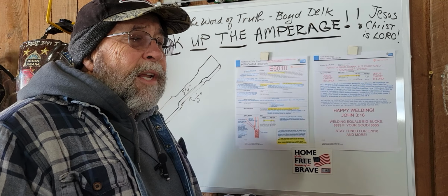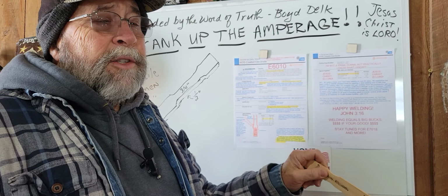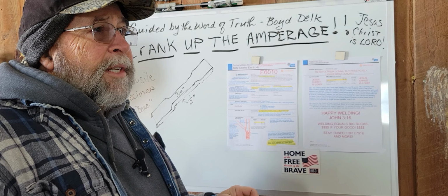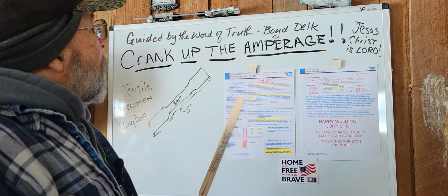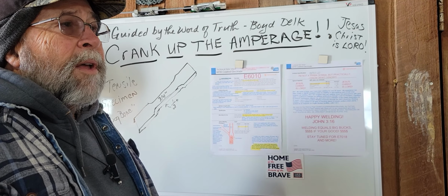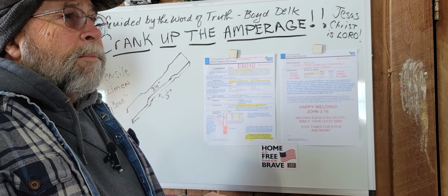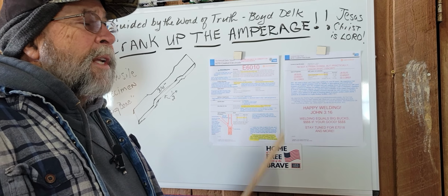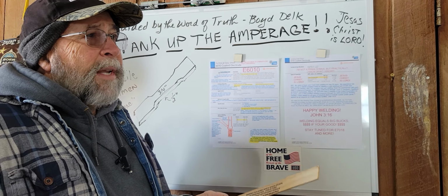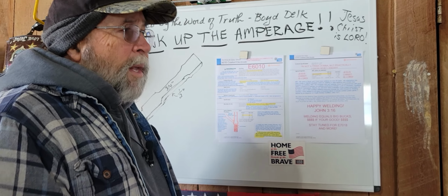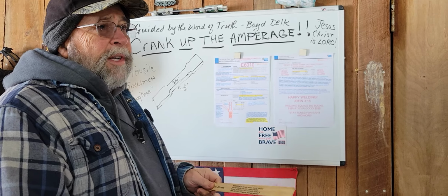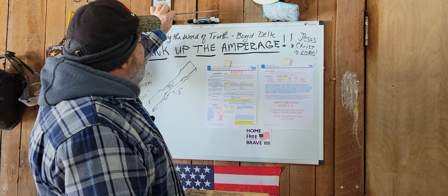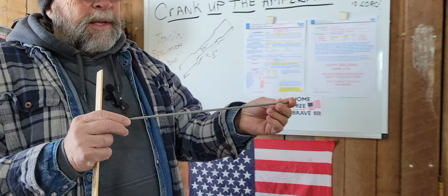It's designed within itself to get deep penetration into the base metal, and primarily base metal of mild steel as well, mild carbon steel. However, on some welding machines, you have arc force adjustments, which basically has a +1, 2, 3, or a -1, 2, 3. Arc force, think of it this way, is like digging a hole with a shovel. The greater the arc force, the more dig this welding machine is going to help this rod, which is designed for dig from the get-go, to dig into the base metal.